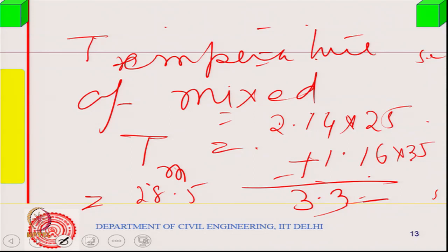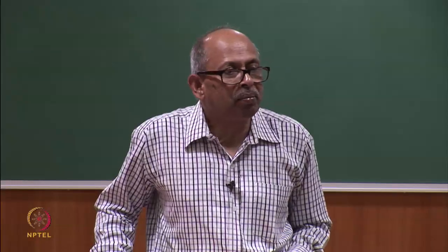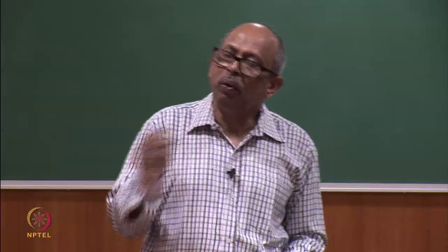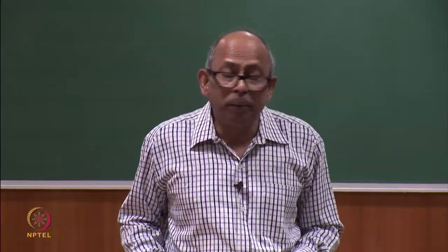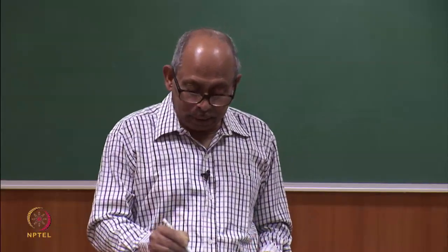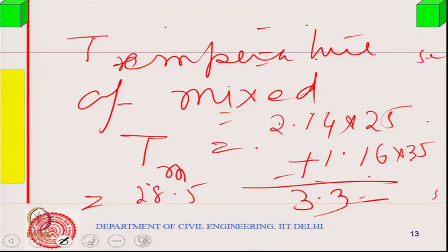Now, I also want to find out the moisture content of the mixture. For that, first I have to go to the psychrometric chart, because the moisture content of the outside air is known to me from the psychrometric chart.